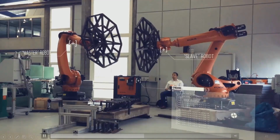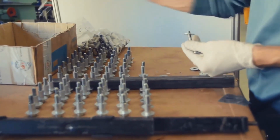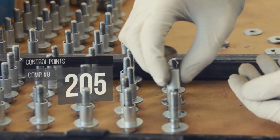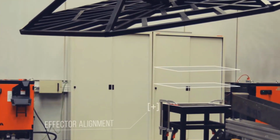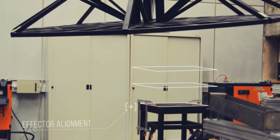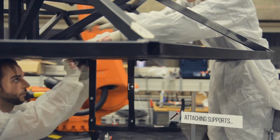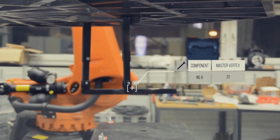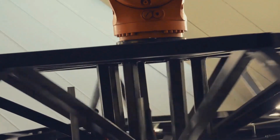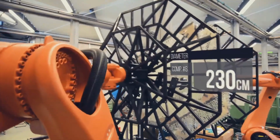So we used two robots that were synchronized. They were running on a master-slave system, which allowed us a very simple control of the movements. Why we used that is that we didn't need any sort of additional support or mold on which to wind. So the two robots would have adjustable frames on each of their end effectors, and then by moving synchronously, the fibers could be winded upon them without needing a very strong structure in between.